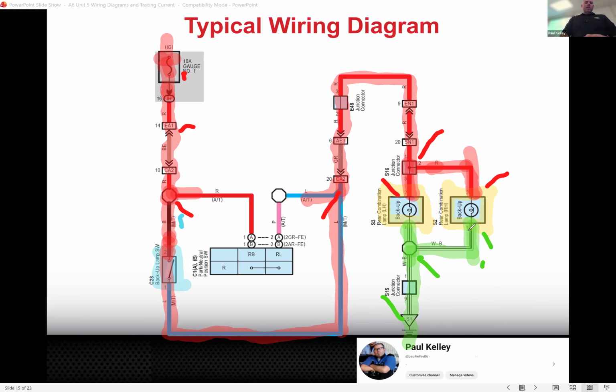Now, let's say I jump on the car and I get a measurement of 0. What are your thoughts? Technically, it could be anywhere between EA1 and, well, even up to IG. If we had a problem with the ignition switch, that would mean it wouldn't get voltage down to that fuse. But then probably a bunch of things wouldn't get powered up, so it'd be a slightly different concern, which is why I normally start by zooming out.